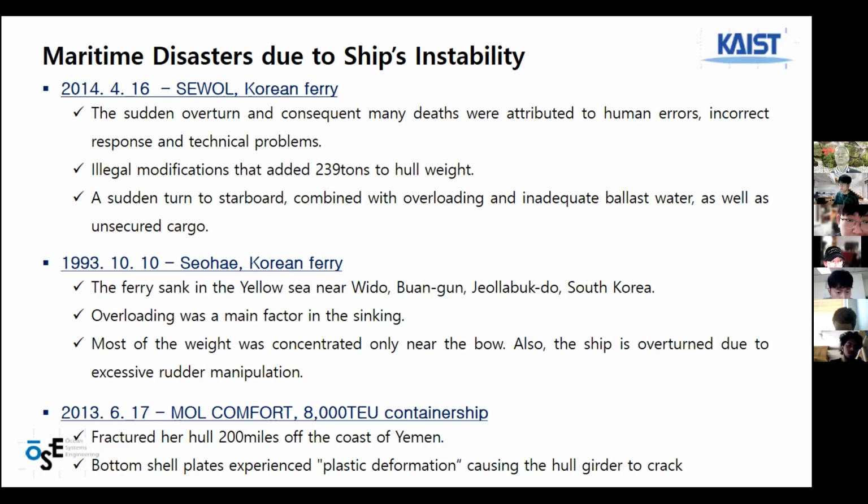And finally, this is a container ship accident, the MOL Comfort. This is one of the most notable rollover accidents of a container ship. It was caused by a hull girder crack. The bottom shell plates experienced fast deformation, so they fractured.